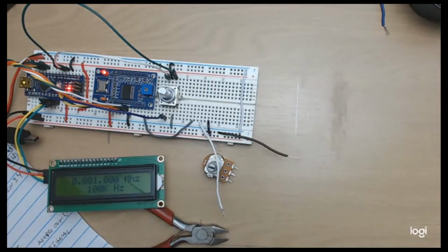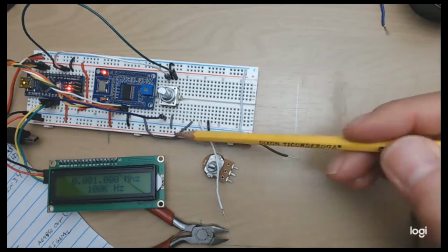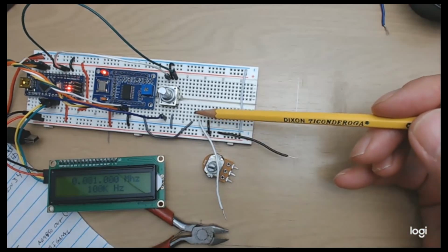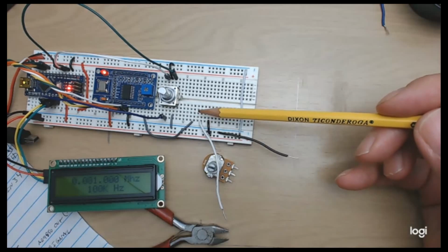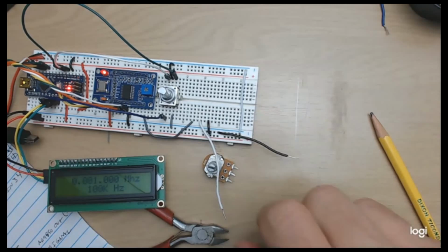But that does not tell me that the frequency generator is actually generating a frequency. All it tells me is that the controls are working and the display is working. In order to see if the frequency generator is actually generating a signal, I need to hook up the output. The way we're wired up, the output signal, a sine wave, comes out on this gray wire here over to here, and that's where we're going to put our 10K linear potentiometer, because that's going to be our attenuator that's going to allow us to turn the amplitude up and down.